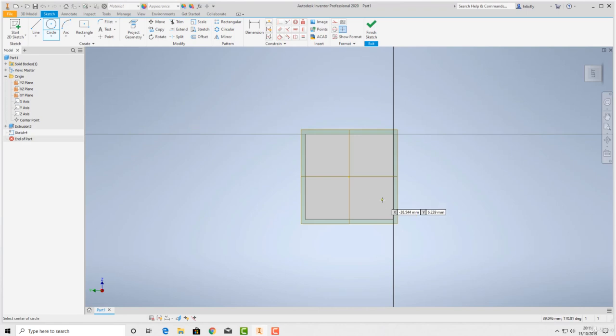So if you left click that, the first point, like with the center rectangle, is the center of the circle. Okay, so if you go near the center point, you'll see again it goes green and snaps to it, so we can click that, and then if we pull this out, it's asking for one dimension, which is the diameter of our circle. So we're going to use 25. Type in 25, enter, and we have a 25mm diameter circle. Okay.